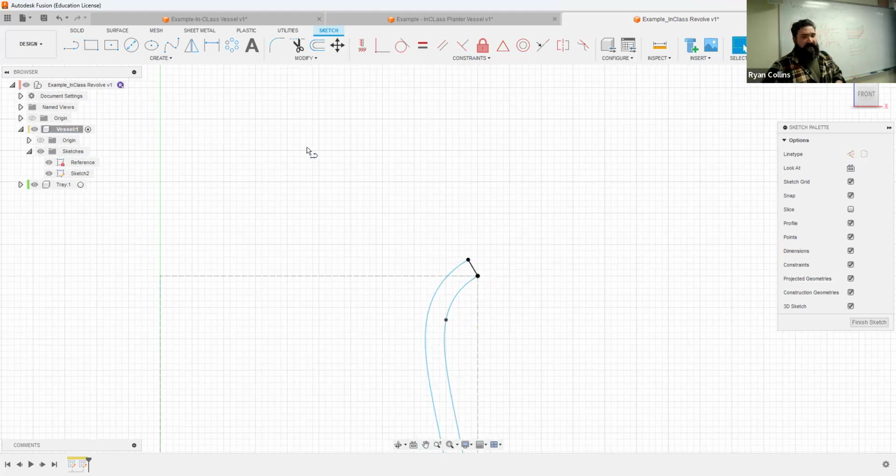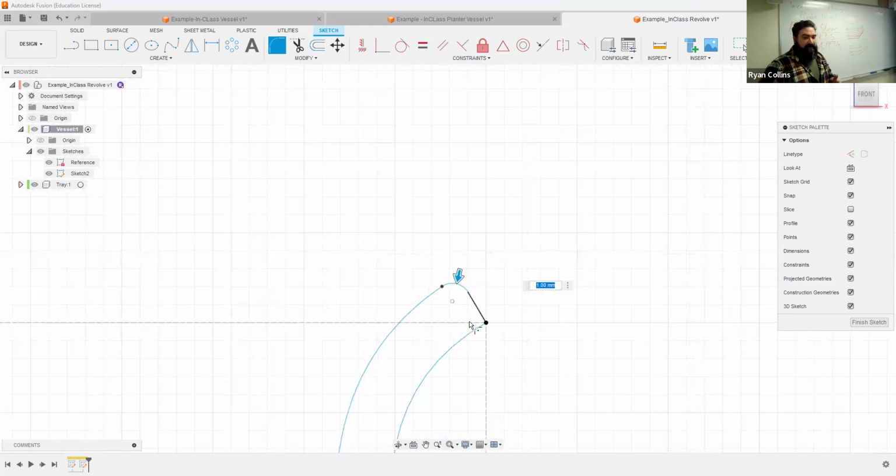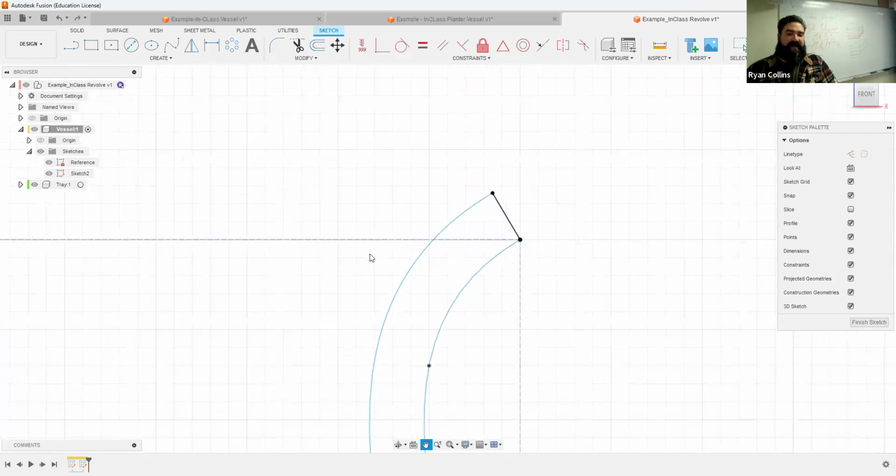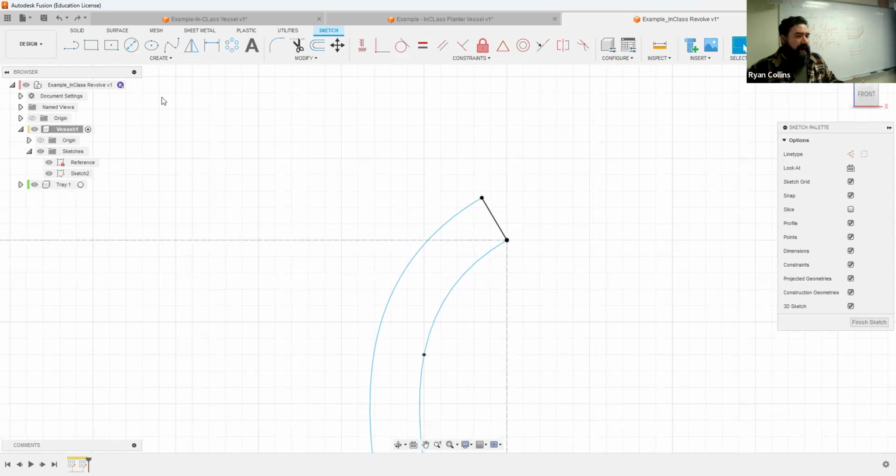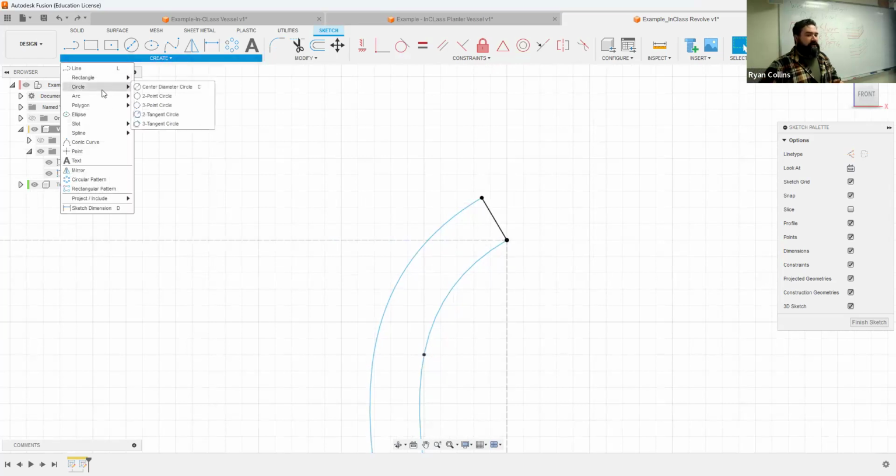We can always add fillets, stuff like that later. Fillets right now get kind of awkward because it is a curved line, but if you add fillets to the sketch, that's fine. You can add these separately, or if you want these both to be the same radius, the same curve, do not hit enter yet. Keep selecting, and those will be the same. So now, if I use a slider, changes this super wonky. So this is why I say I would not recommend using the fillet right now. You can do that later. So let's just Control Z that and make it flat. If you do want to make this round right now, I would recommend actually using, instead of a straight line, use a 2-point circle.